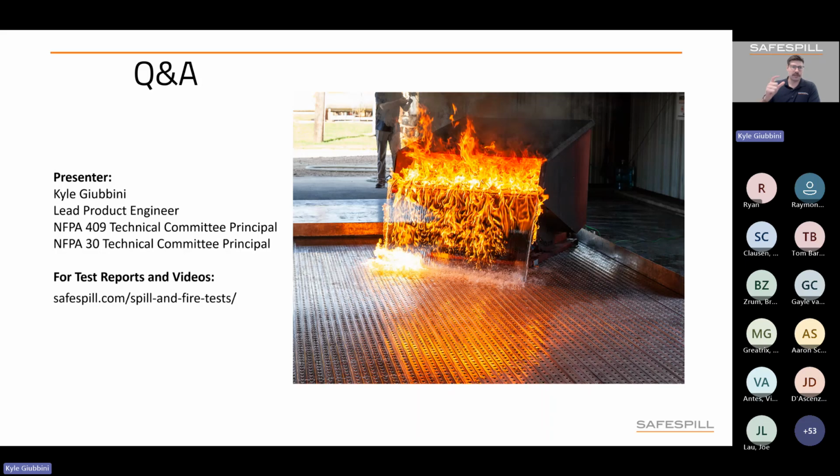So hopefully we answered this. That monoslope from back wall to hangar door is often an advantageous approach, but depending on the facility, we've gone into facilities where it's a retrofit and there may not be an existing slope to it, or maybe the building or structure has already been designed with no slope, and so we do need to put kind of intermediate slopes in there. So hopefully that answers your question, David.